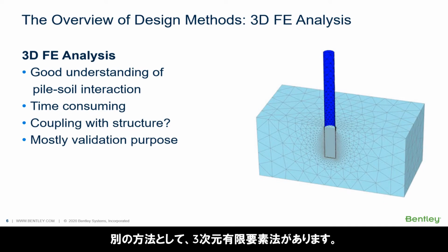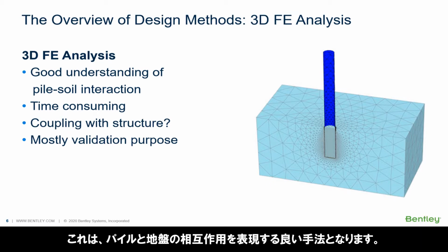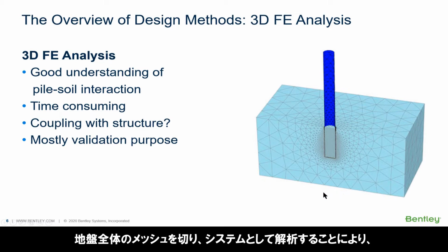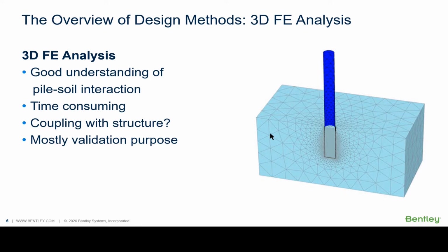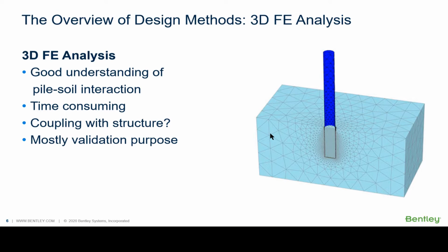The other way is to use the three-dimensional finite element method. As we know, this gives us a very detailed understanding of pile-soil interaction. I mean, modeling the whole volume of the soil and solving the system gives us the most reliable result. However, we need to carry out each analysis for one load case, one geometry, and one soil property.